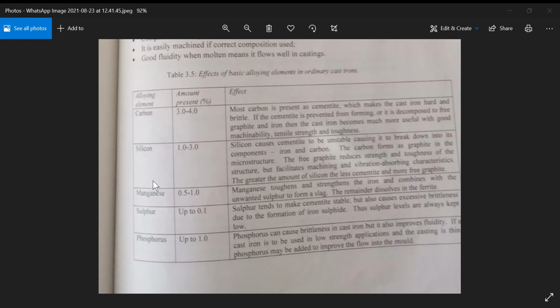So it now has tensile strength double that of fine gray cast iron. So this has better tensile strength as compared to this, because those sharp edges are no longer there. And where is it used? Well, it's used in brake discs and drums.